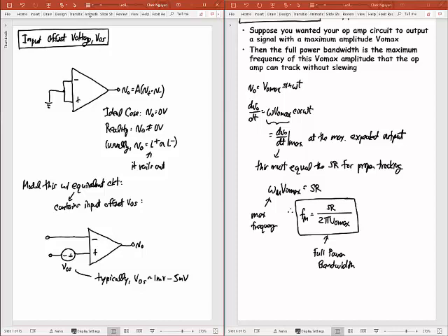Okay? The other, but you may argue that, okay, I'm never going to use my op amp without feedback. And that's true. You probably will not use the op amp without feedback. This is one of the reasons why you won't, right? Because it'll just rail out. Okay, the other reason is because the bandwidth would be horrible. It would be omega B, which is on the order of, we should talk about order of magnitude for these op amps. For the 741 op amp you have in lab, actually you measure that, don't you? Now let me not say what it is. We'll talk about order of magnitude after you're done with your lab. But those are always good to have in your head, numbers. Have numbers in your head.